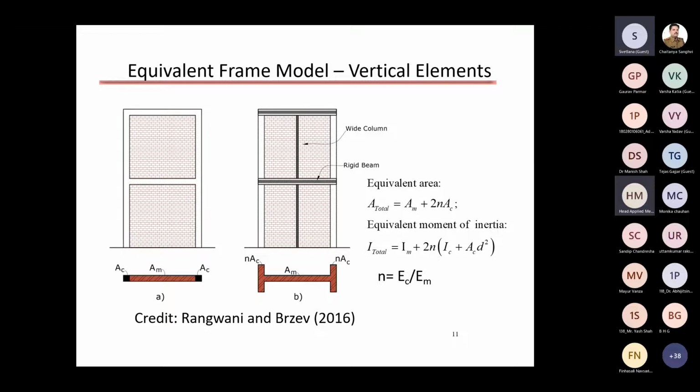So let us focus on the big things and model them, and we should get good enough results. So here we have the masonry section on B, which, as you can see, is an I-shaped section. The thickness of the flange is equal to the thickness of the wall, and the size of the web, web of the I section, and flanges are equal to N times AC.